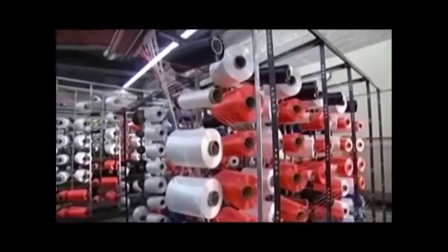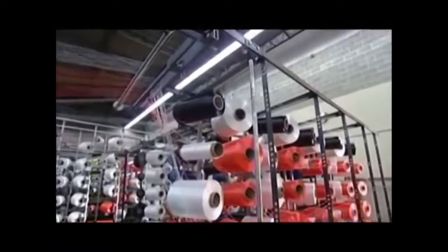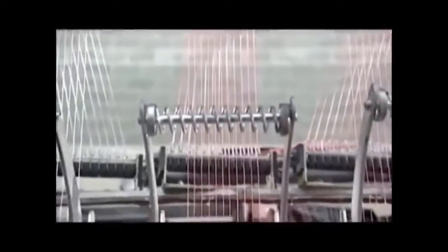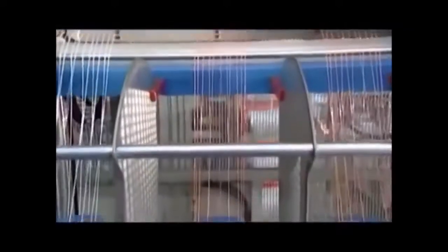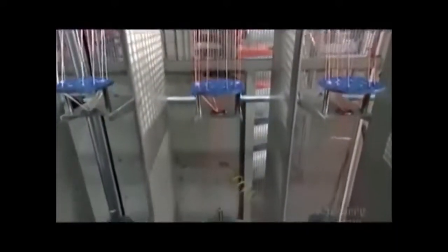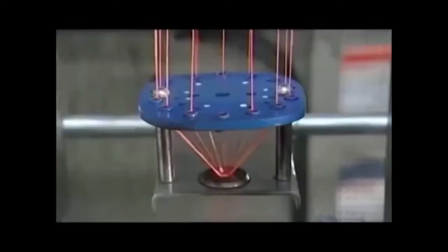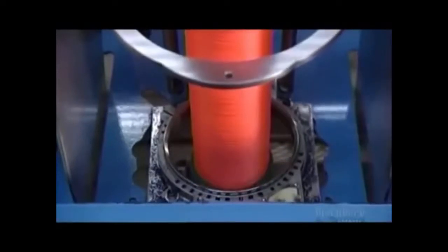Now, dozens of spools of nylon fiber unwind at the same time to make jackets to protect the core yarns. The fibers travel several meters over a network of rollers that act as guides and control tension on each individual fiber. They pass through distribution plates, as turning bobbins below twist the fibers into yarn. The platform moves up and down to evenly wind the yarn onto the bobbin.